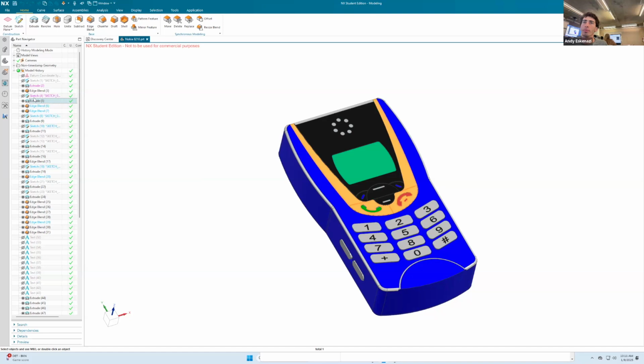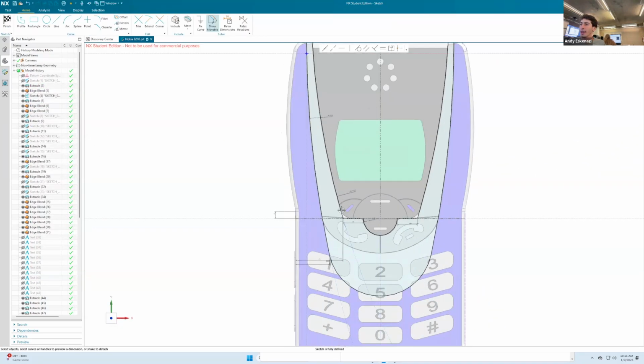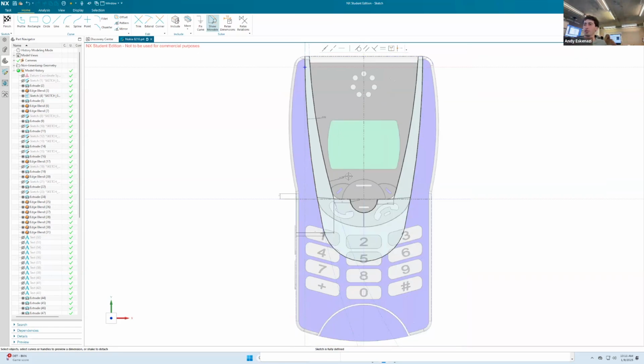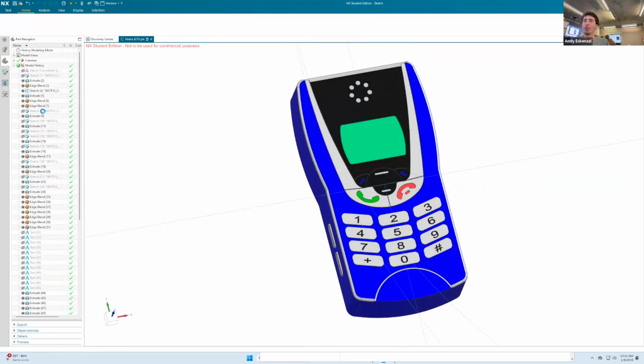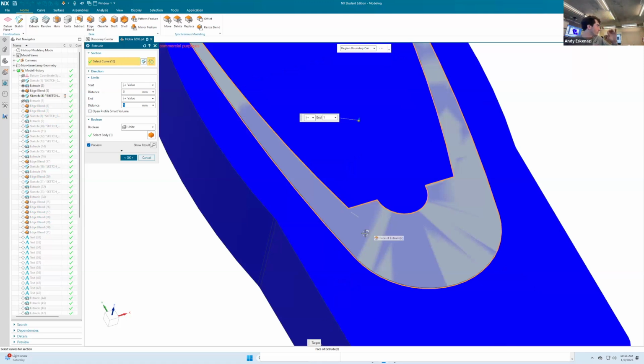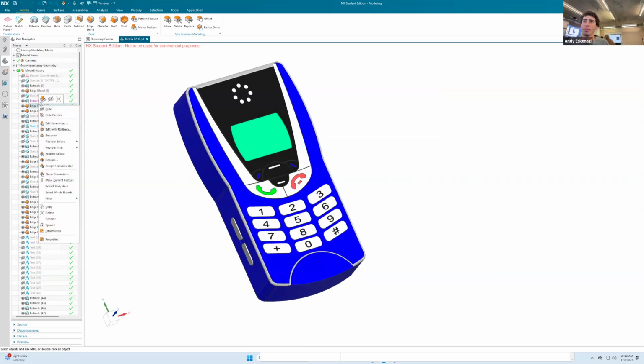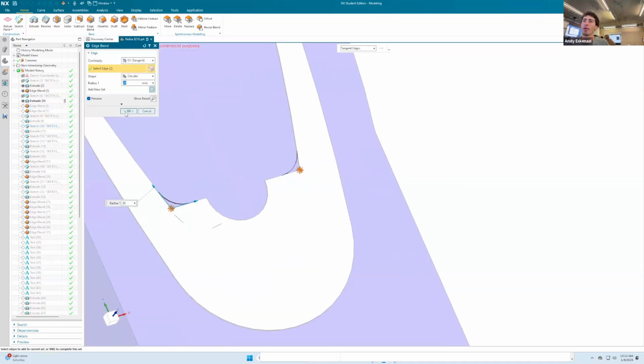And then what did I extrude? I did another sketch on the top face of the phone, just to start giving it some decorations, drawing a couple of lines. Again, I'm not particularly happy with this design, but you can make it whatever you want, right? Then I extruded that upwards by a very tiny amount. I want this to be barely noticeable, but noticeable enough that I can color it and make it look nice. I clicked OK, and then where's that edge blend? Let me edit. Right, so I made that round in there.